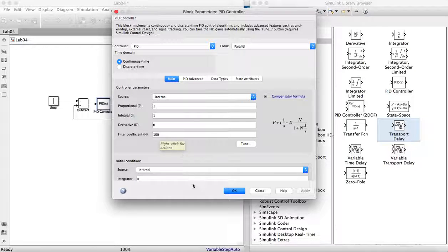The next important thing that we note is that while we are able to input our controller parameters directly, Simulink has access to the MATLAB workspace. So by writing a script in MATLAB, Simulink would also have access to that information. For now, we will define everything by parameters as variables. Instead of inputting numbers in proportional, integral, and derivative, we just put a variable, and then later we will define it in MATLAB.